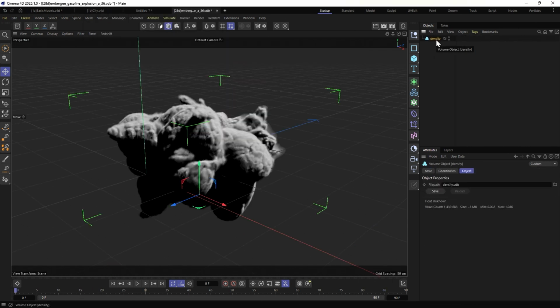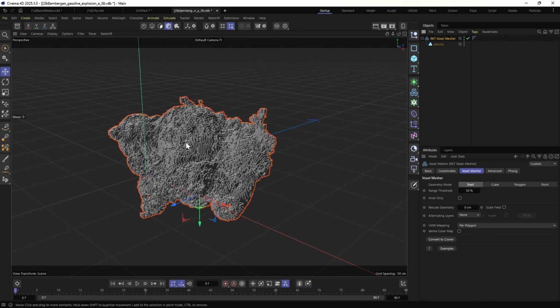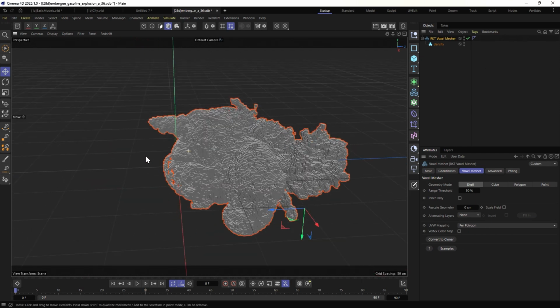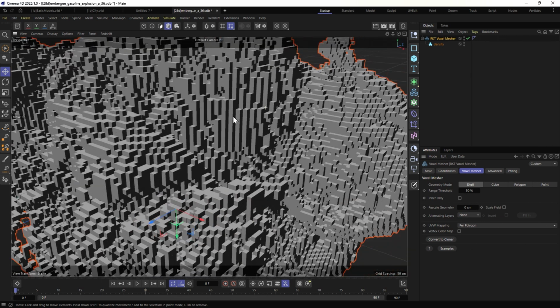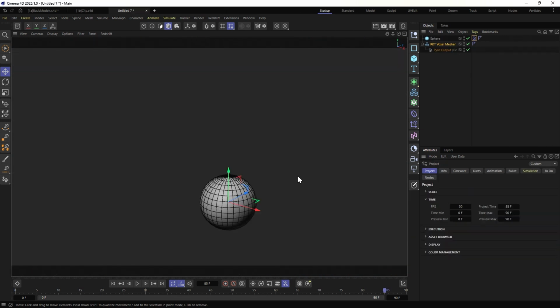And much like Pyro, this is generating its own voxels. So I can just feed this directly into a voxel mesher, holding down Alt or Option. It'll get fed in, and the instant I do, you can see that, again, we are getting this volume of the density automatically represented as all these lovely individual cubes. So that is all the ways that we can feed something in to get Voxel Mesher to generate something for us.